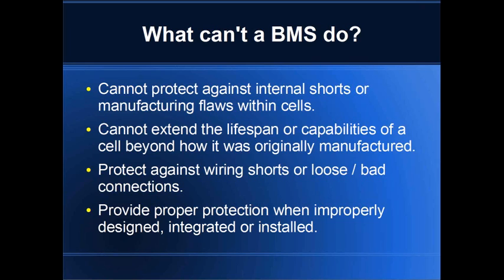But if you have a short that develops inside the battery pack before any type of switches, the BMS can again detect it usually, but it can't really do anything if there's no switch provided to shut that off. If you have a bus bar, for example, directly above a metal plate, and whatever is insulating it breaks, and the two terminals of the battery short against the plate, unless you happen to have some type of a switch in there, the battery management system is not going to be able to do much about that. So proper design is still important there.